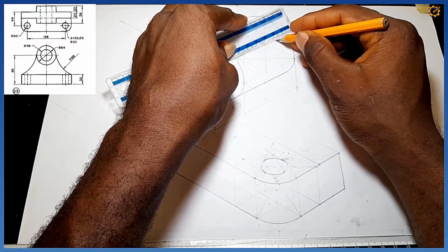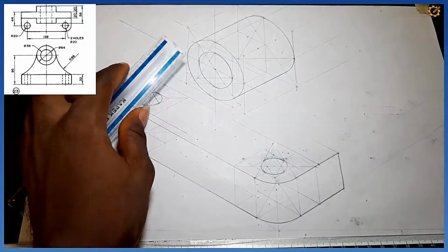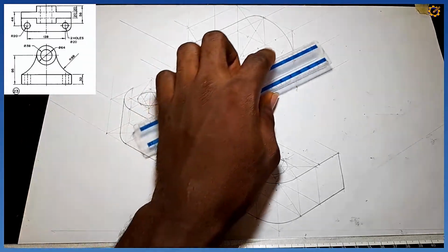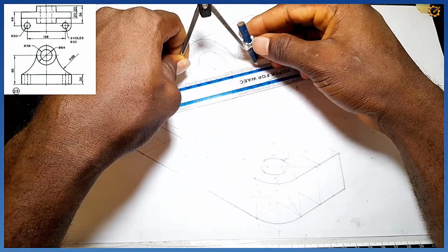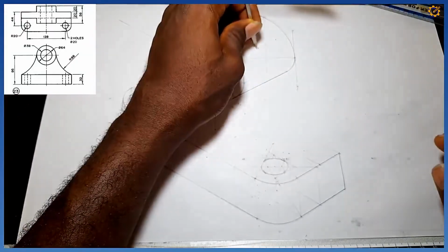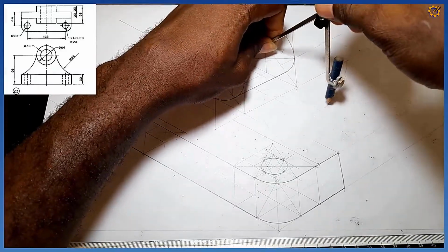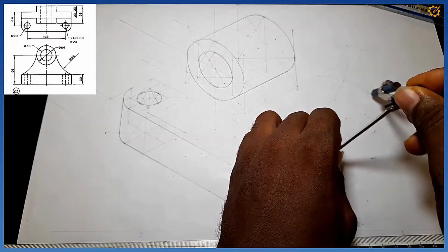First mark 20, then here to here was 20, so it is sitting from here to here. And we are told that the radius of that arc is radius 88. So I'm going to pick my compass, measure radius 88, and with radius 88, this first mark here, first of all, I draw this, you can see faintly. Then this first mark here also faintly.